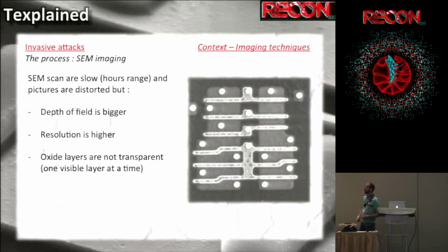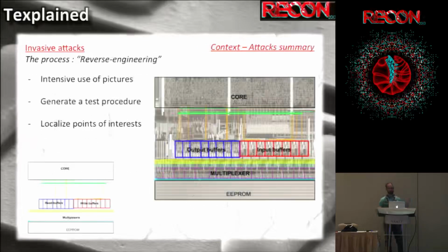I see the active areas, I see the polysilicon gates, I see the contacts, the tungsten plugs. I see everything, so I feel all right because I have a lot of information on my picture and I don't miss any. So once you made the right choice and you scan your chip this way, you can just put pictures together and you can start to study things.